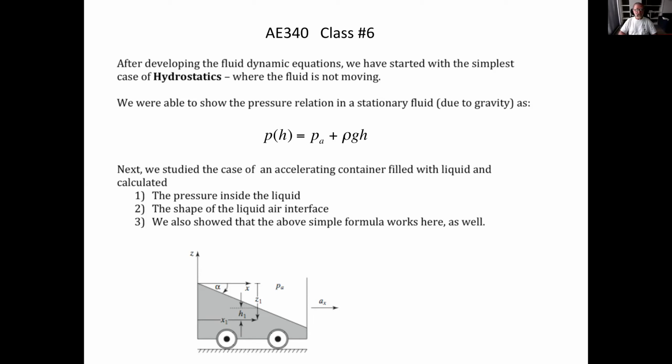And the first case was the little container like a fish tank, which is shown in the bottom right here. Let me get the pen. Like here, this is this case. And if it accelerates to the right, the fluid probably going to assume a different shape. And we stressed that it is stationary, although the whole system is accelerating. So the fluid particles are not moving, therefore disqualify as hydrostatic.